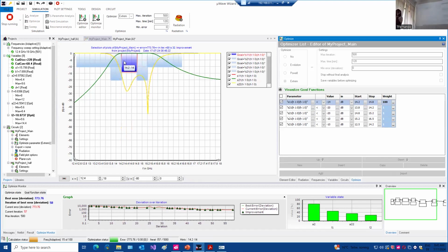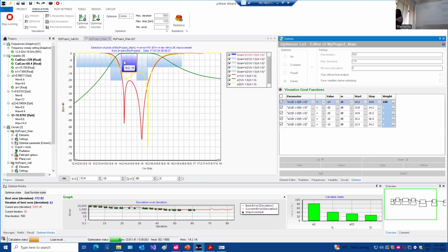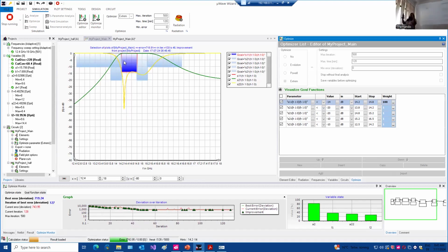order of the filter, as I said before, corresponds to the number of cavities. We have 3 cavities only. So sometimes it can happen the 3 cavities are not enough. We have to expand the number of cavities. It may not be crucial for this example, but when you have a wider bandwidth for your filter, you may need more and more cavities to satisfy this requirement.